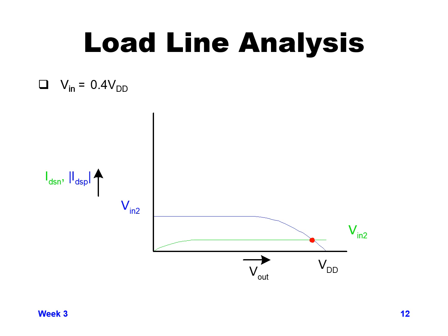Now let's go to Vn equals 0.4 times VDD. This is the Vn2 curves of the previous slide. So here you can see the green curve is now a little bit higher. The blue curve is starting to get lower. The green curve meets the blue curve, still close to VDD, but it's not quite VDD anymore. Maybe 90% of VDD or so here. And you can see there's starting to be a little bit of current flow, measurable current flow. It's not close to 0 anymore. So that's interesting to note.